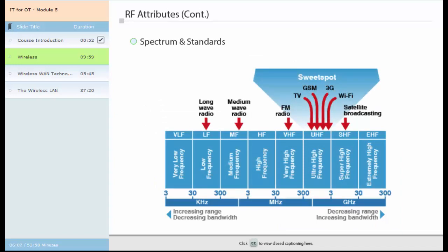Some common unlicensed bands in the United States are 2.4 GHz, used by Wi-Fi and Bluetooth technologies, 5 GHz, made popular by 802.11a, 24 GHz, wireless backhaul, and 60 GHz and up, 802.11ad draft specifications, also commonly found in proximity sensors in newer vehicles.